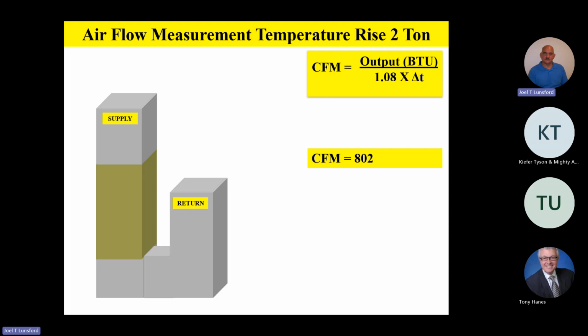So just by energizing your heat strip and selecting the speed tap you want and plugging in a little math, you can actually determine the airflow that's moving through that unit. And by the way, fellas, this is extremely accurate. It's going to get you within a couple percentage points of an airflow hood. This is very, very tight airflow. It's a lot tighter than you'd think it'd be in a field application, but it's all simple math, and it works very, very well. I've used this method for years on air handlers, a quick, easy, fast way to determine airflow moving through a unit. When I go out and commission or take a look at a job, if I have a problem job, it used to be when I was in the field, I used this a lot.